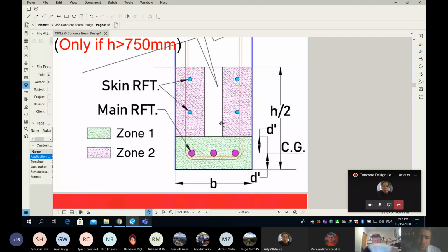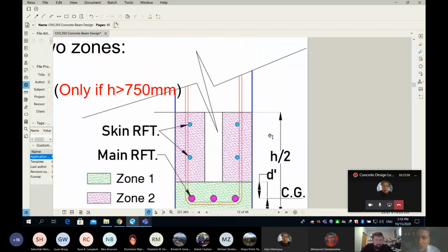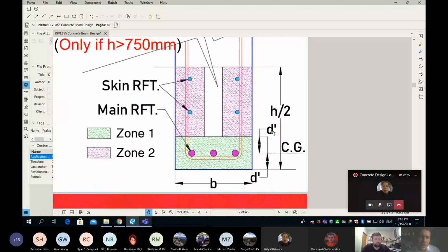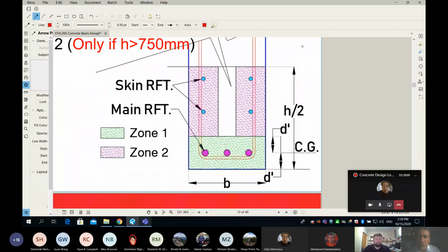Again, for simplicity, we will say, you know what? Anything from half the beam down has an issue, or may have an issue. Anything above the half of the beam is in compression, and then we don't have to worry about it because compression closes the crack. Okay, and you can see this line here is the half of the beam. And you can see I labeled here H/2.